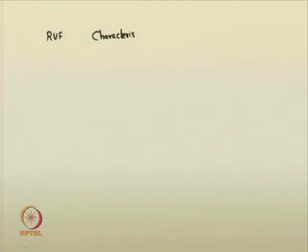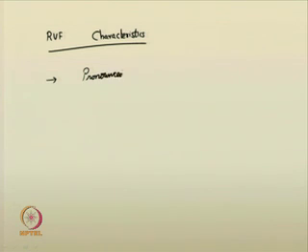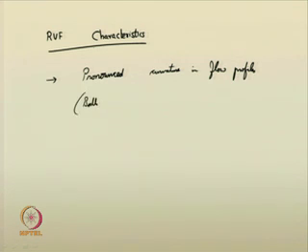What are the rapidly varied flow characteristics? How can I suggest that a flow is rapidly varied flow? What are its general characteristics? As we mentioned earlier, rapidly varied flow will have pronounced curvature in flow profiles, both water surface as well as streamline.